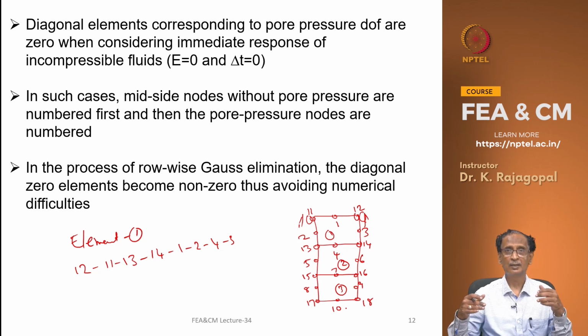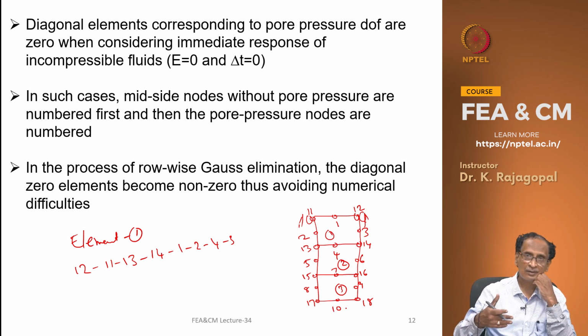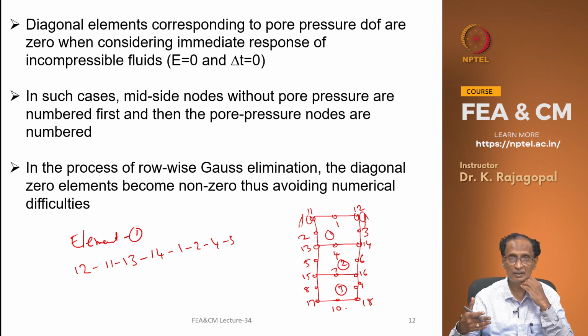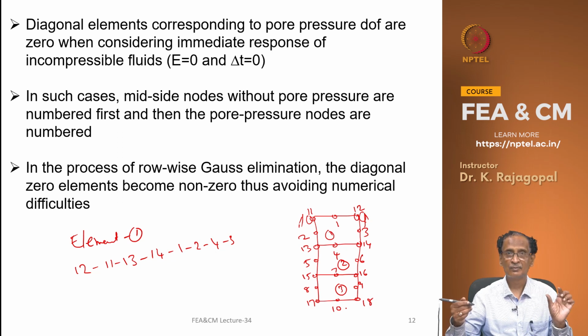we can also incorporate the influence of the increase in the soil strength because of consolidation, and so that is an advancement. So, especially if you are doing analysis of any construction on a soft clay, we should go in for consolidation analysis and then go for models like modified Cam clay or soft clay models that can include the influence of the void ratio on the strength of the soil.